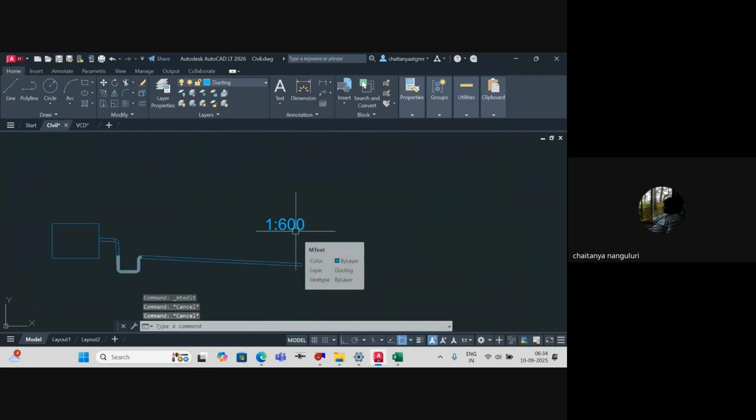Okay, this is the worst case thing that you have to consider. But generally, we try to do plumbing rules only, which is 1 is to 100. Understood or not? Theoretically, we say worst case is, minimum slope that you have to maintain is 1 inch per every 50 feet of piping. Clear?